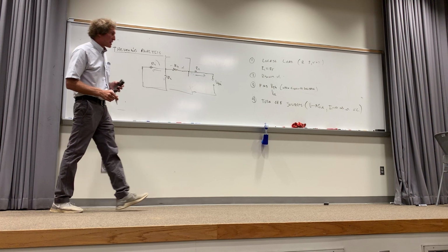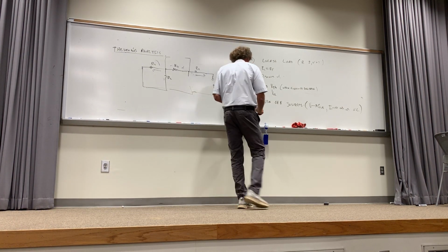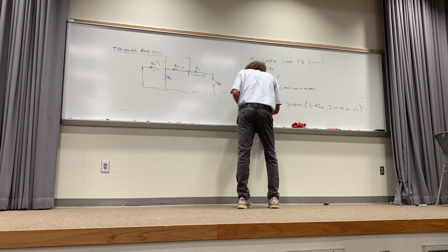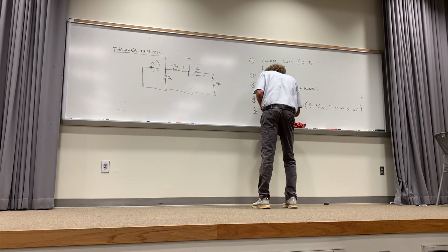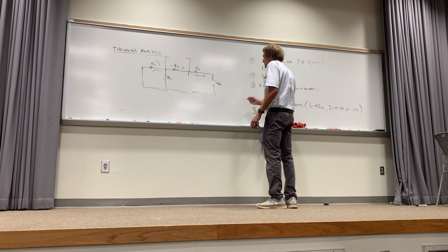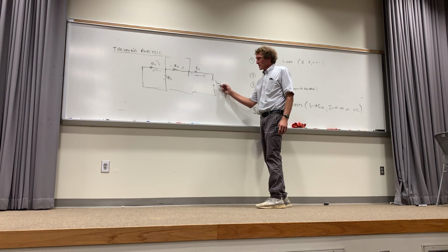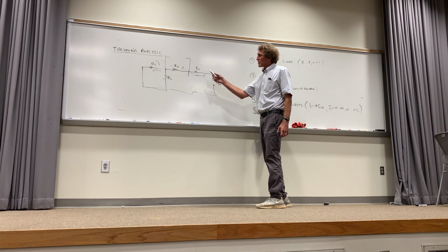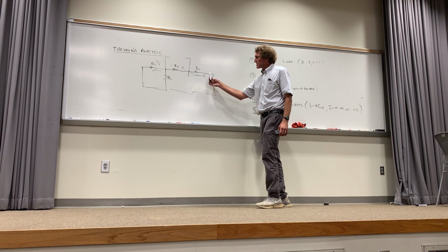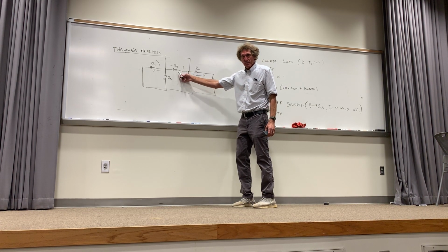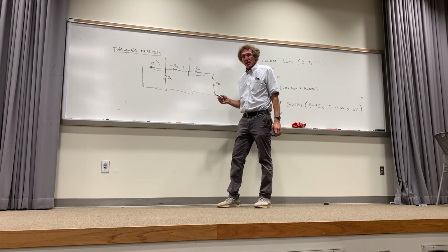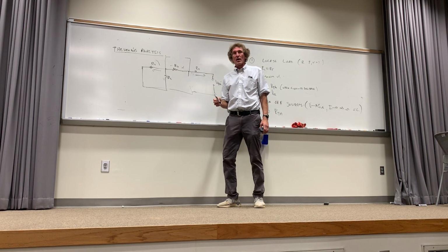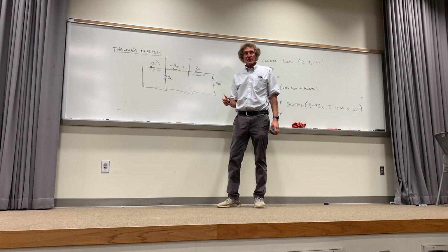And then the fifth thing is find RTH, or really the resistance between these two terminals. Do you follow me in this class? Now for this one, I did this on purpose to make it a little more complicated than it need be. If I look at the resistance, this would be in series with this, right? So R3 plus R4, and these two would be in parallel, plus the parallel combination of R2 and R1, right? That would be the net resistance.